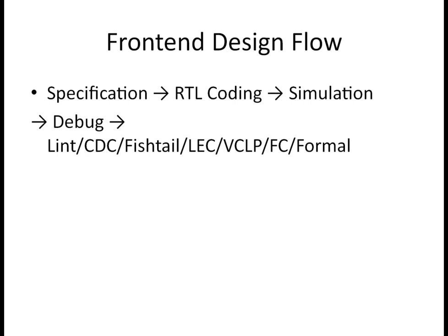Next, the one we get most often in our project is bit width mismatch, where you are assigning a 3-bit signal to 2-bit, or 4-bit to 3-bit.